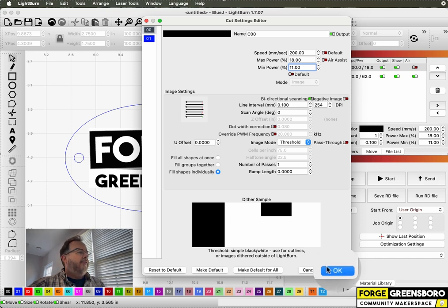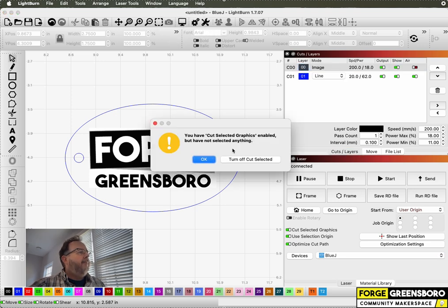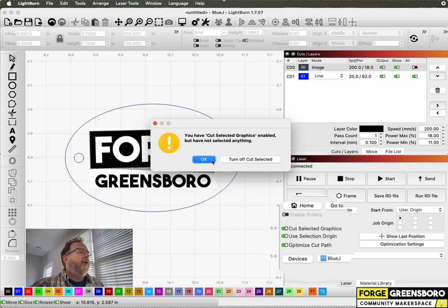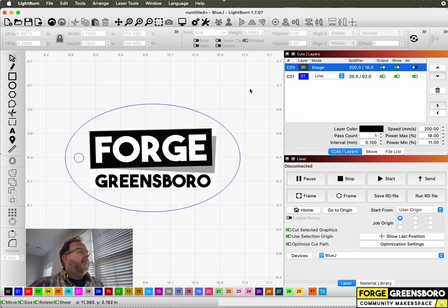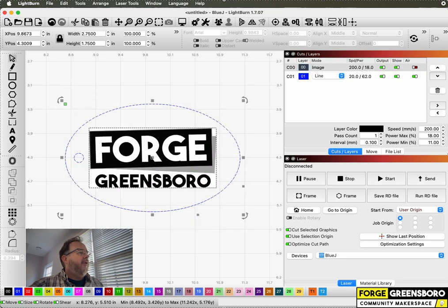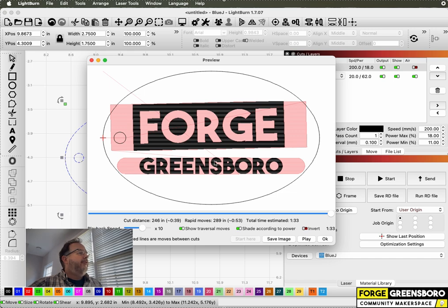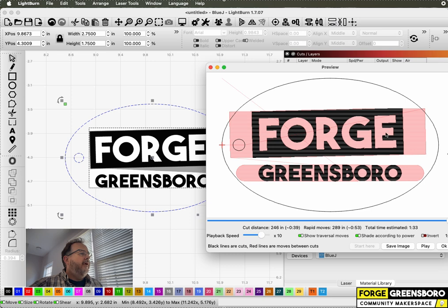If I just say OK here and preview my job, well, I have cut selected graphics turned on, which the computers at the Forge usually also have turned on. So it says, well, I can't preview anything because you have nothing selected. So I'm going to dismiss that and select all the stuff. Now I'm going to hit preview. And you will see that the drop shadow here is ignored. That's because it's not dark enough, so it's treated as solid white.